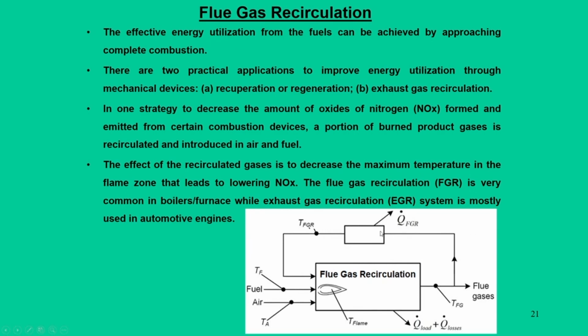Through this process, we can tap this heat. At the same time, whatever unburnt fuel is there can be recirculated with the fresh charge, and as a result you can get an effective combustion. One advantage of this is that we can lower the NOx formation. That is the essential advantage of this recirculation.